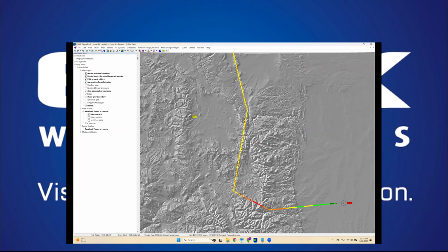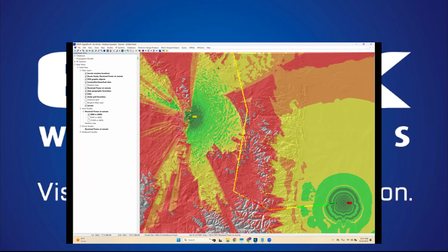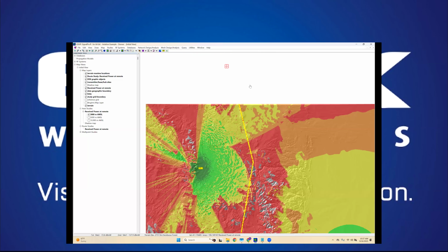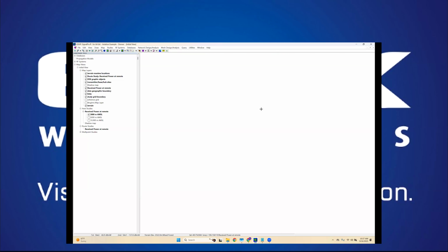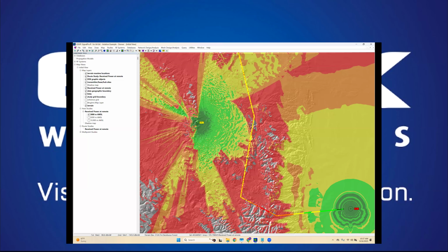And so in this case, if I go back to my area study, you can see that the route started out at 3,000 meters here, and way down here, it's showing the same result as my area study for 3,000 meters. We don't have connectivity, but as it starts to ascend up, it picks up that signal earlier than just my area study. So in this way, we can plot a complex flight path, including all its variation in heights, and show the performance along that path.